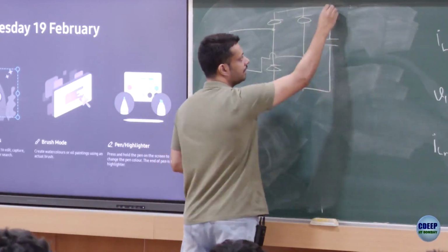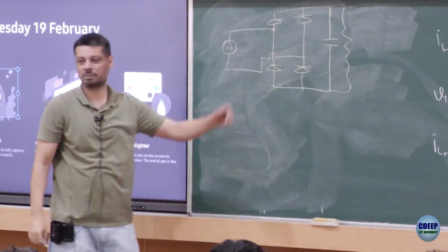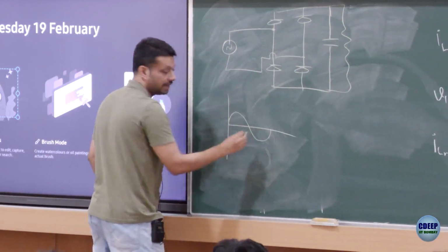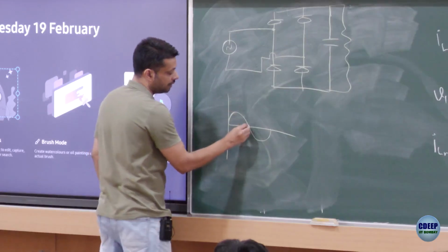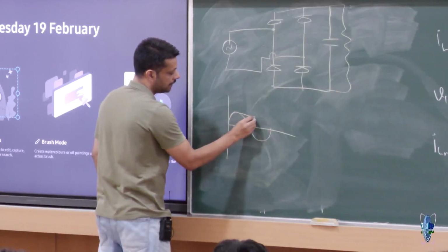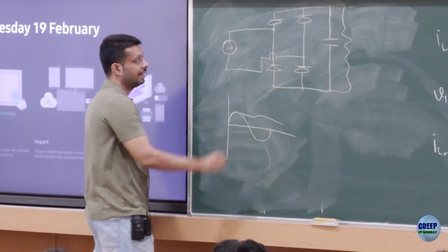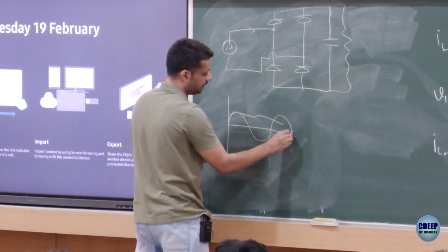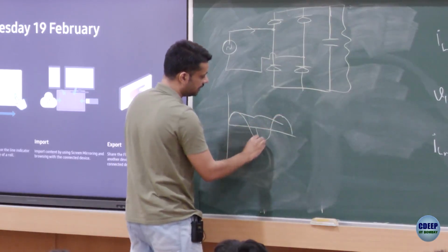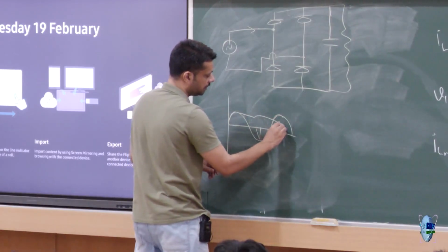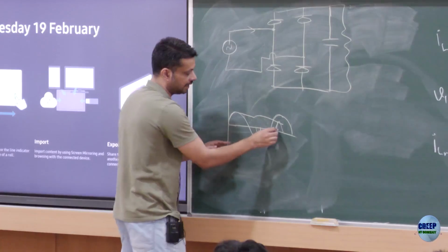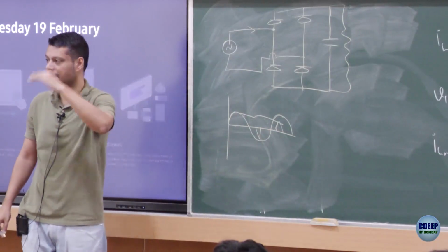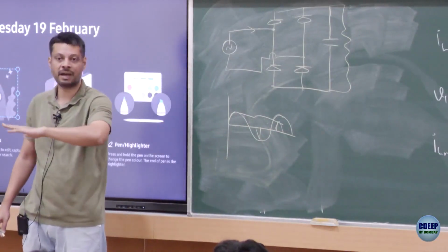Capacitor and a resistor, because most of the power supplies would have this kind of thing. So in this case, we understand if the input voltage is like this, the output voltage would be like this, right? Keep going, and the current that you are drawing, after it settles down, will have a negative peak here, some positive peak here, and so on. So if you see the current here, it would be half-wave symmetric. That means whatever happens in the positive cycle, the same thing happens in the negative cycle with a negative magnitude